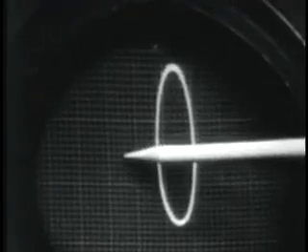Remember, ER is greater in amplitude than EC. Since I have ER applied to the vertical deflection plates and EC applied to the horizontal deflection plates, we will have an oval at 90 degrees rather than a perfect circle. So we have indicated we have two voltages 90 degrees out of phase with the amplitude of one greater than the other, or ER is greater in amplitude than EC, and the two voltages are 90 degrees out of phase.